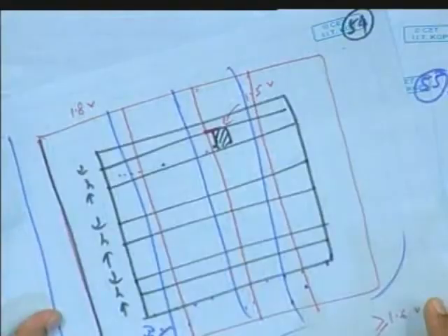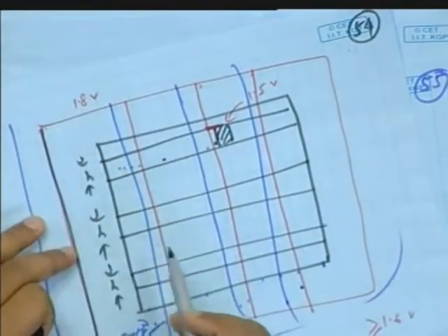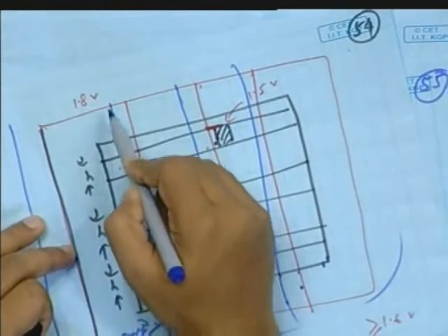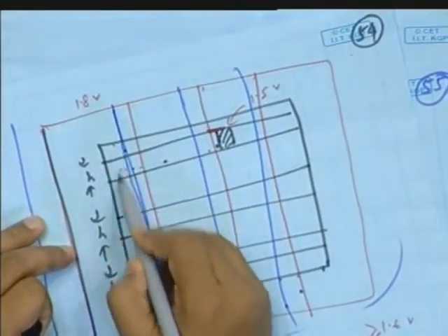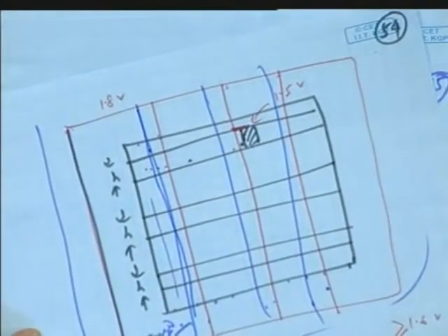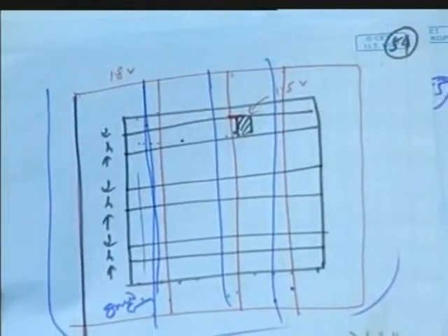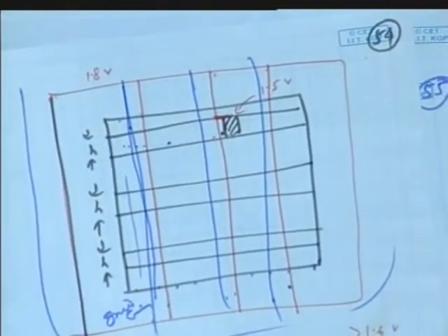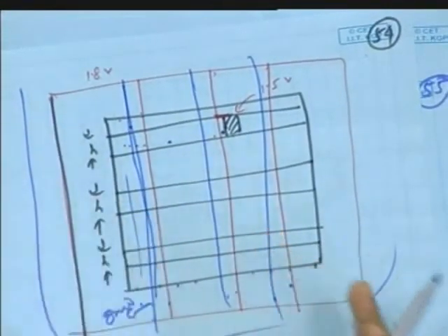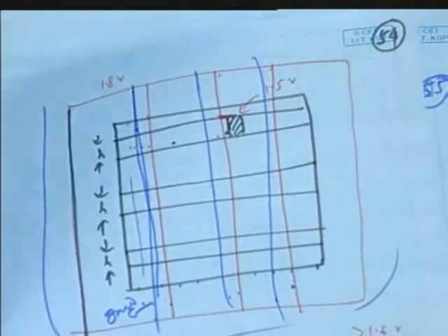Now my question is, to reduce the interference, you can do that. If this is my strap, you do not use some neighborhood of that strap, and the rest you can use. What is the point there? That will also do the same thing, right? So it depends on your experience. If you have a small chip and you have 6 layers, you can dedicatedly give one layer, metal 1, and you can skip, no problem.